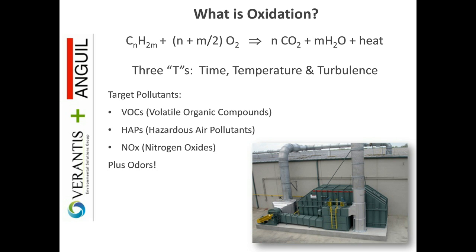and more heat. Now this applies to all of those thermal oxidizer technologies I had just mentioned. The equation is the same for the catalytic unit as well. The only difference is there's a catalyst present just to lower that operating temperature. And the other reason I like to put this in here is it's important to note that oxidation is an exothermic reaction. So in some of these cases there is a lot of heat generated just through the oxidation process. And the amount of heat that's generated many times dictates which of the technologies we'll lean